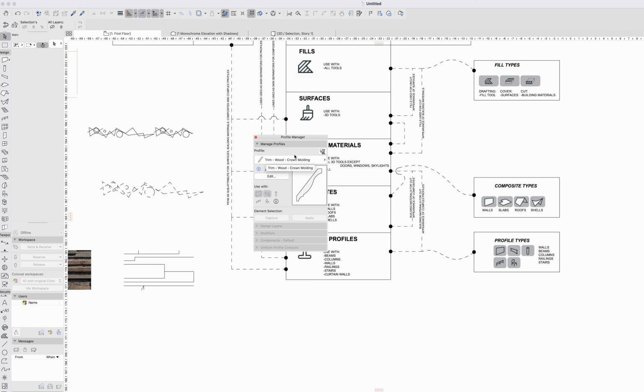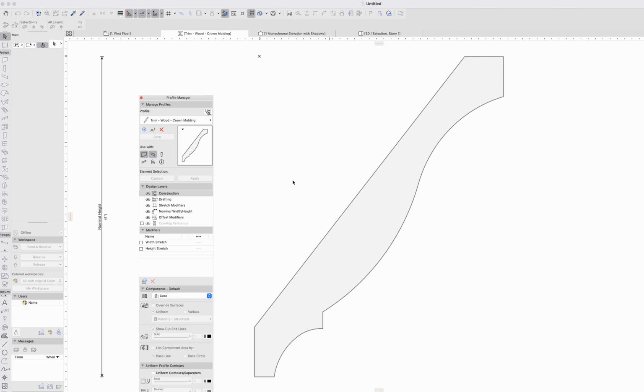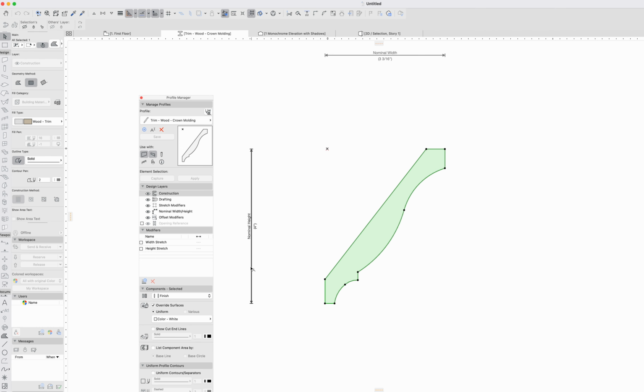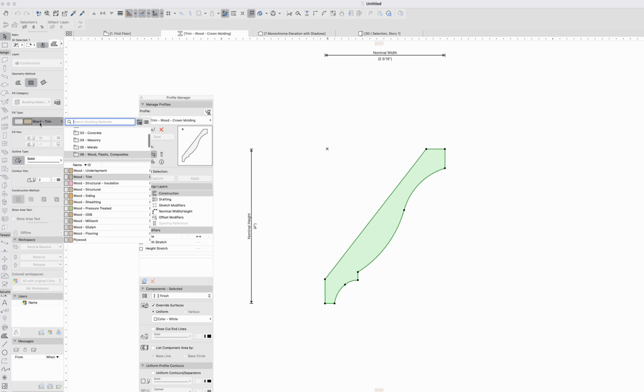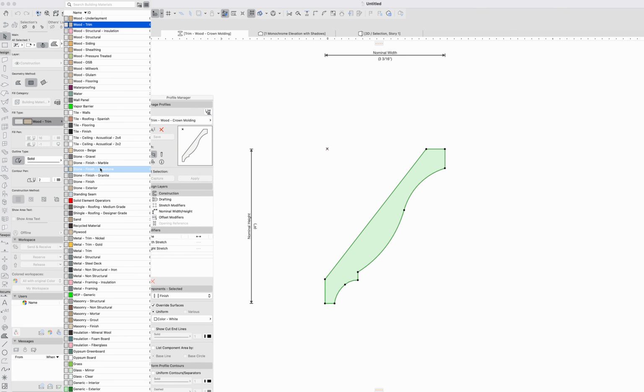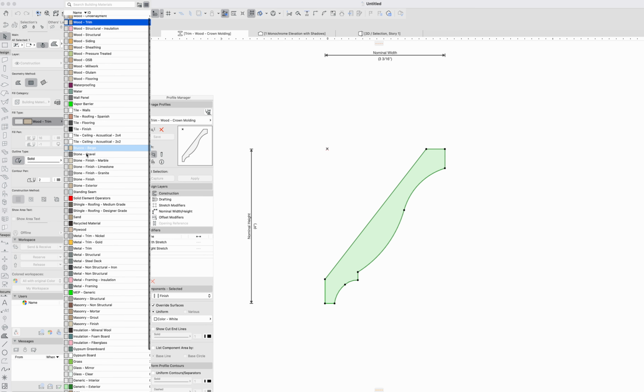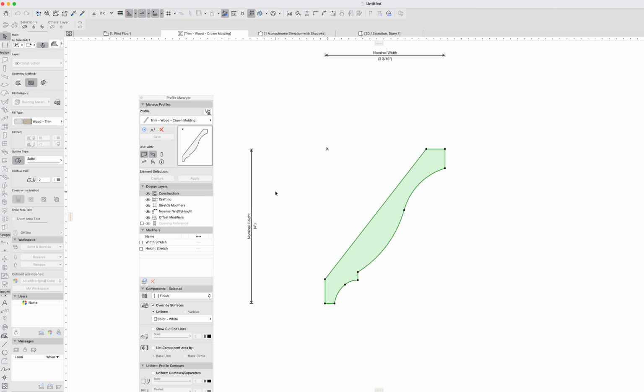So if we look at this, we have options here under the edit menu. It actually pulls up a little drafting aid. We can see that this is a fill type, right? They have to be fill extrusions. And the building material list is the only thing we have access to here. So it's limited to just building material extrusions in the composite editor. The building materials, similar to the composites, can be core, finish, or other in their extrusions.